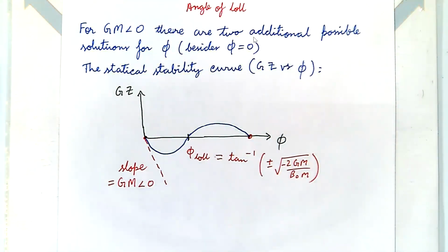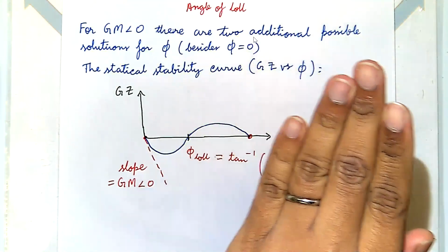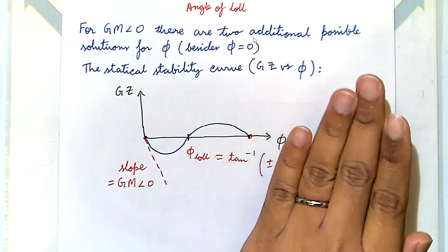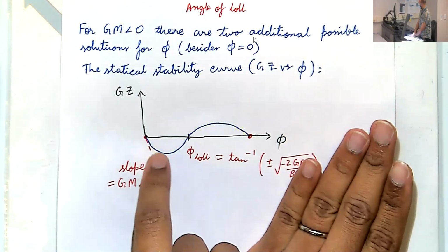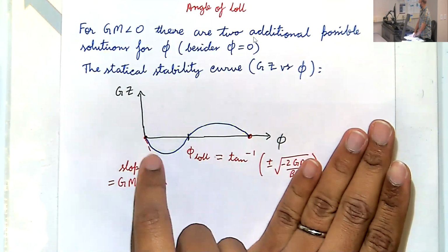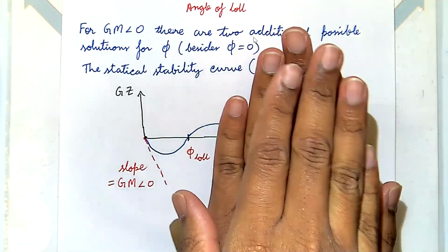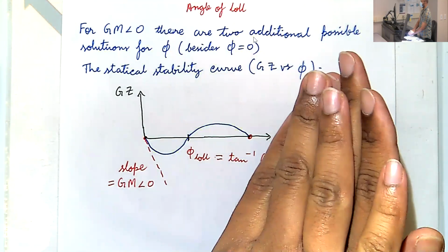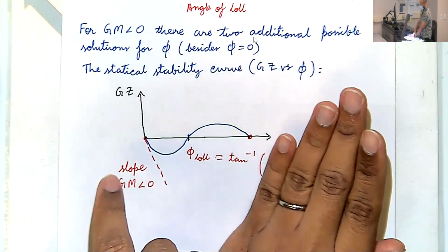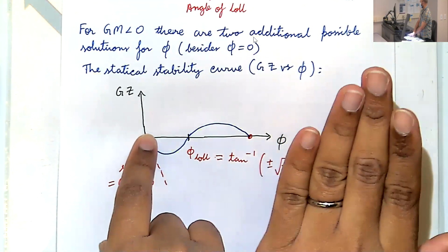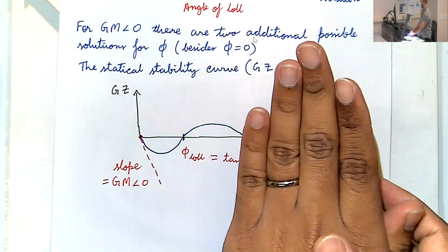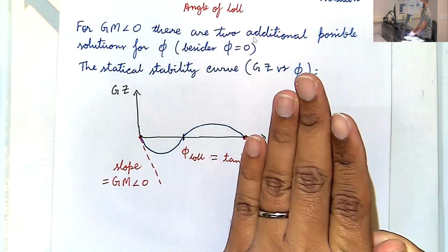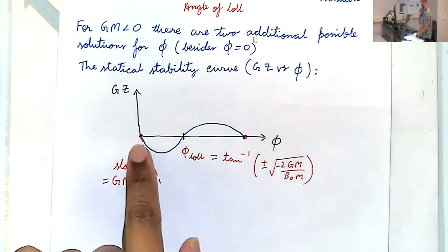I would say it would go further down to, would it be the minimum GZ that's less than 0? Okay, so you're saying it would come here. And think about what negative GZ means. It's saying you don't have any torque trying to restore you. You have a torque that's trying to further imbalance you. Okay, so if you move even a little bit, you will have what's the opposite of restoring? Disturbing, destabilizing. Yeah, you have a destabilizing torque, right?